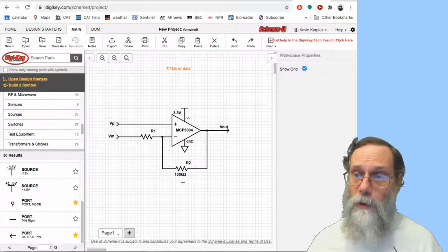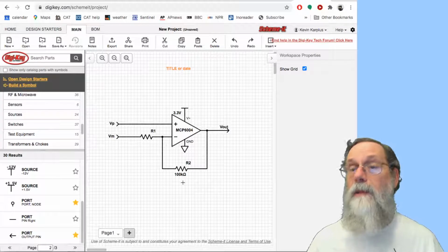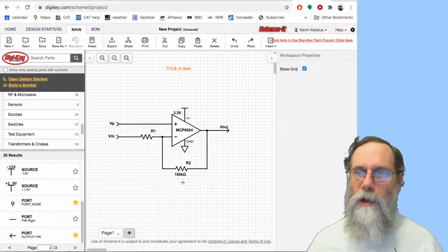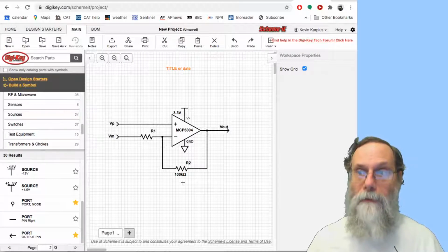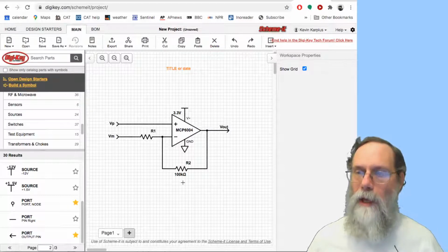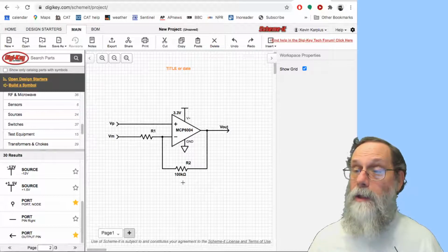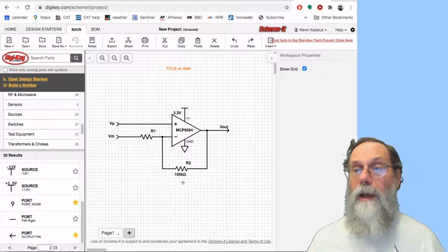Now, sometimes in the early stages of design, you can say, I want a negative feedback over here, but I don't know the values yet. And so you just have names R1, R2. In your final schematics, the ones that you use to build from, put the values in. Because a large fraction of the errors that I see students making in their labs when they do the design is they put in a different component value than what they intended to. They intended to put in 100 kilo ohms and they put in 100 ohms.